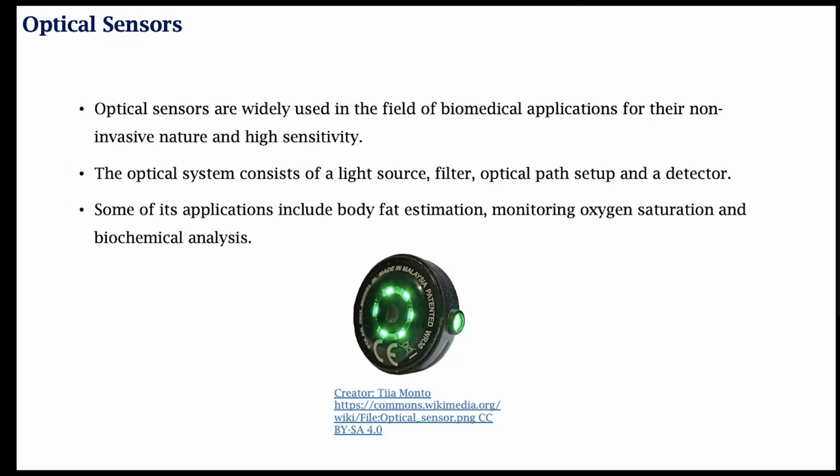So first, we started out with resistive sensors such as strain gauges. We discussed various types of strain gauges, foil strain gauges, different materials that are used, constantan and nickel. And we said silicon strain gauges. What are the advantages, temperature sensitivity of these? Then we looked at thermistors, special negative temperature coefficient materials that have an exponential relationship with temperature and resistance.